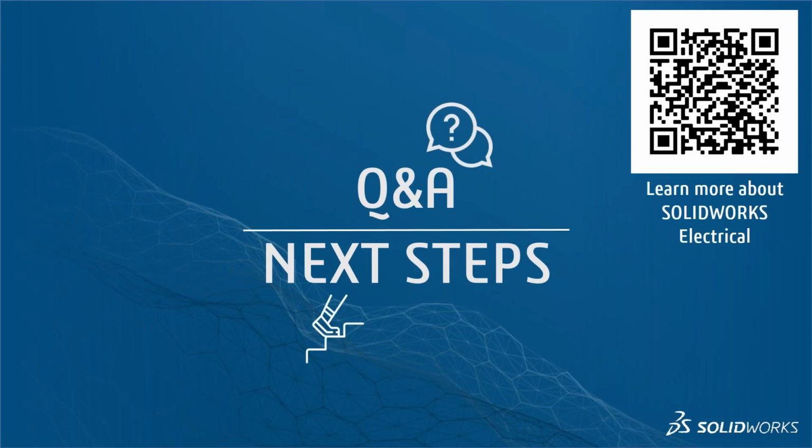I'm going to take a couple questions here real quick. Yes, the wire style can allow for coax. You just have to build the appropriate wire style, right? If it's a coax or triax, you might want to use a multi-wire style to include that. If you want further information or want to talk about that a little bit more, we can go down that path, because you can set that up in your connectors and your symbols as well if you needed to.